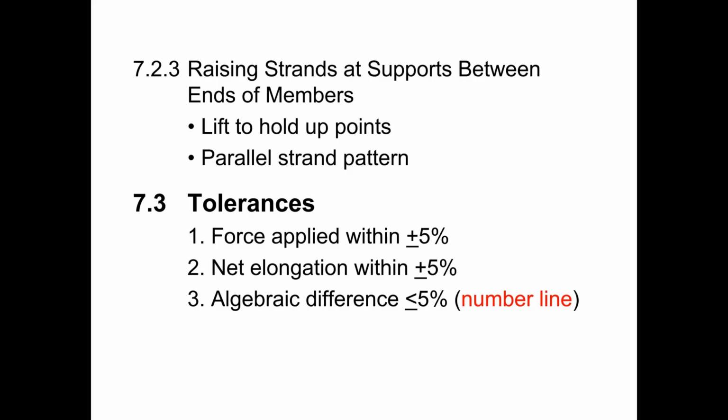Another thing to keep in mind is that when strands are tensioned in the draped position, typically the strands are parallel to each other throughout the length of the bed. And so that means the geometry of the strands is the same from one strand to the next. For all the draped strands, the geometry is going to be the same. And so that means when we're calculating how much force is occurring at those hold-up and hold-down locations, we can do that for one strand and then just multiply by the number of strands, and we've calculated our total force.